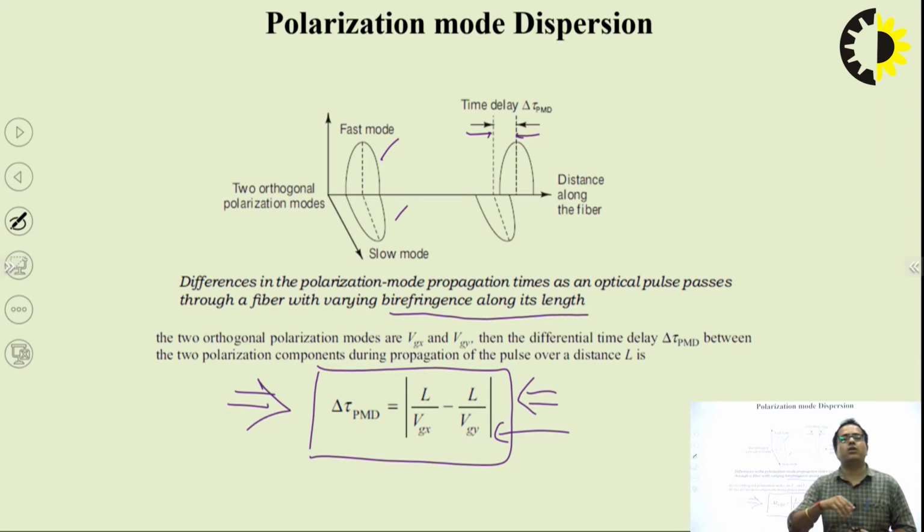Another one is what we call the intrinsic and extrinsic factors that lead to the phenomenon of attenuation. That intrinsic factor is basically because of the material. Your fiber is made up of silica. So if it is made up of silicon dioxide, definitely your silica is bonded with two oxygen atoms, and this molecule will have its resonance frequency.